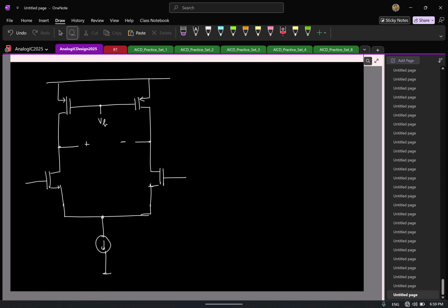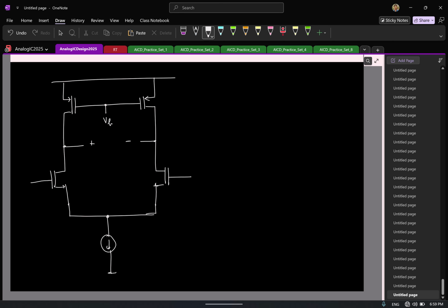Now before going to any small signal business, let's check what's happening to the DC operating point. So let us say the tail current is I0. You apply some bias voltage on the two sides. What can you say about the drain voltages here? I mean, they'll remain the same, fine, but is it defined? Is everyone fine that this drain voltage is not defined? Why is it not defined? Here we have two current sources. They are biased independently. So even if all stars align properly, even if the currents are equal, this voltage will not be defined.